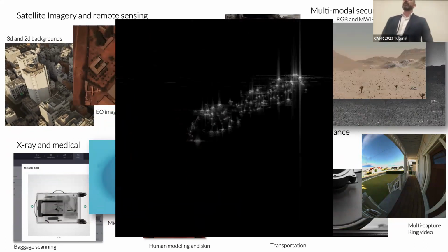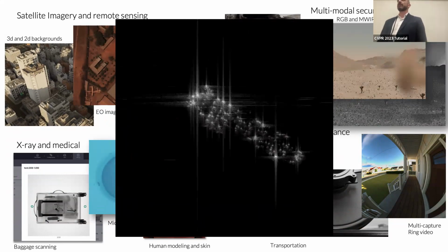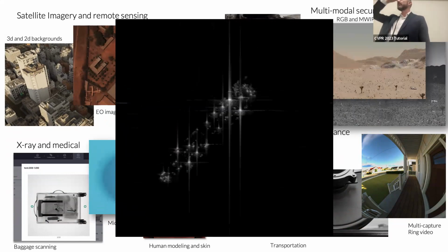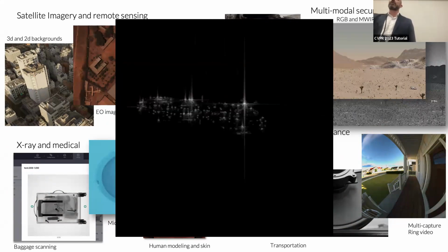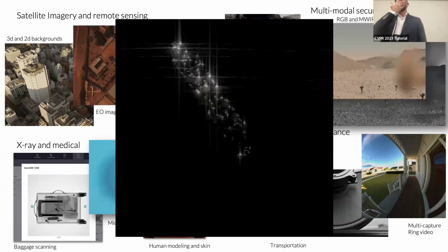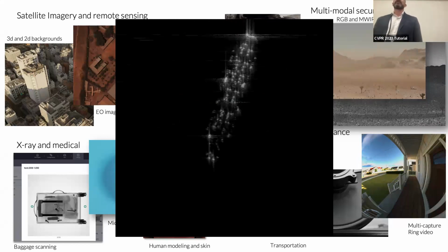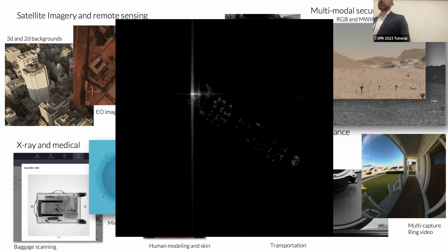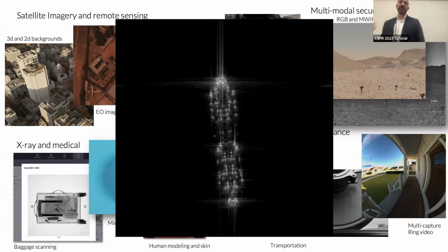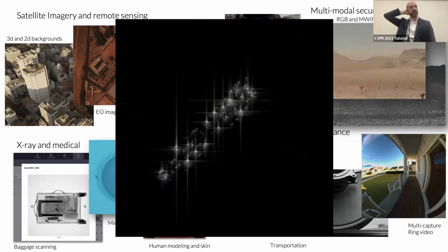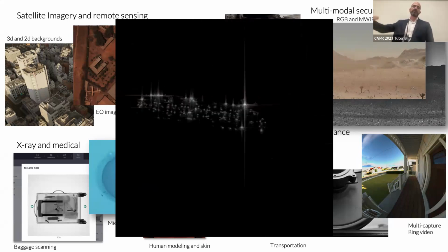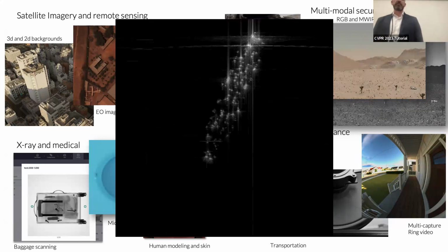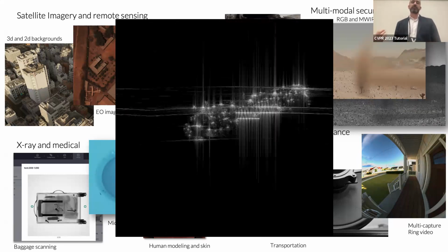We do this, which is called synthetic aperture radar. I'm actually curious, for those people in the audience, how many of you have heard the term synthetic aperture radar before? All right, quite a few. So if you want to do imaging through clouds, through rain, this is a way to do that, where you actually take not a radar image, but tens of thousands of radar images and then post-process them to generate an image. And what we're showing here is a video of a tanker ship as it rotates, showing how different it can look based on the position of the ship relative to the sensor.